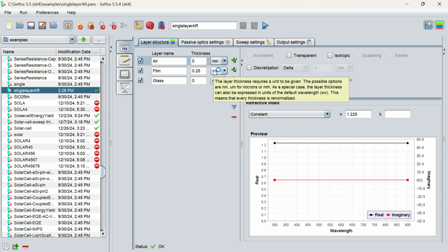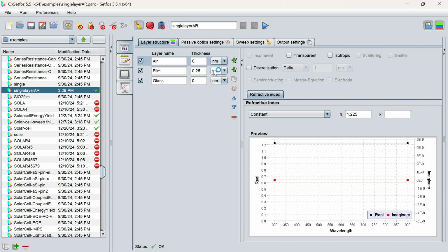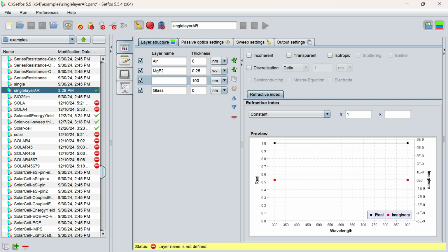Now, if you want to create double layer anti-reflection coating structures, we can design again using quarter wavelength layers. The top layer will be the same, air, but if you want to change that value you can easily change it. For the second layer you can give a new name. It is magnesium fluoride, a colorless to white crystalline inorganic compound with a variety of usage. You can add one more layer here, magnesium oxide, and the thickness you can consider 0.5.